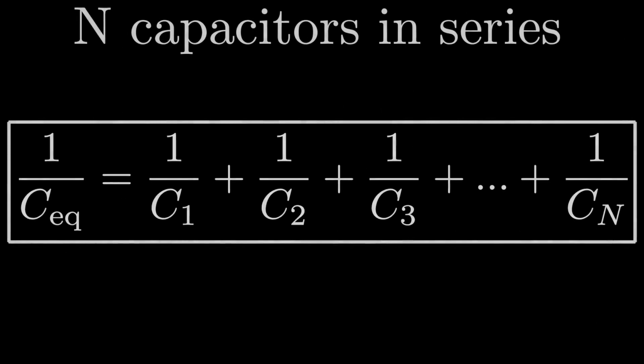So those are our two fundamental ways we can connect two capacitors. If we want to evaluate the capacitance due to a complex system with some in series and some in parallel, we just take it one step at a time, evaluating it piece by piece until we end up with our final result. Let's think about this system right here.